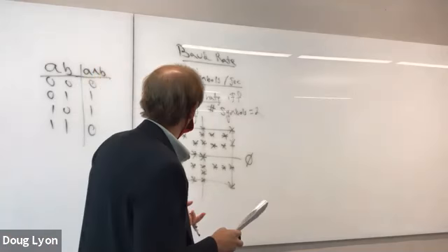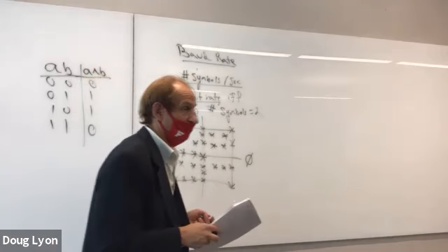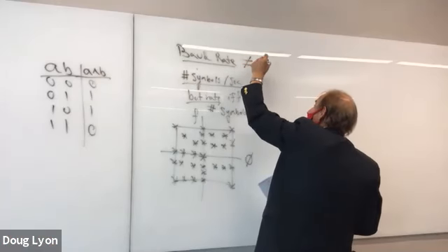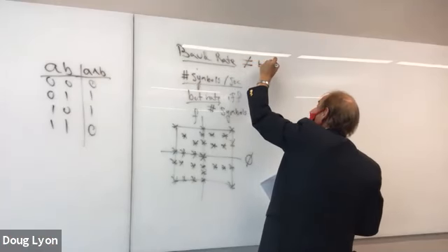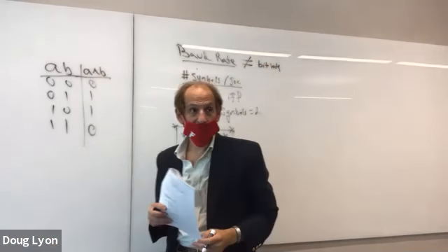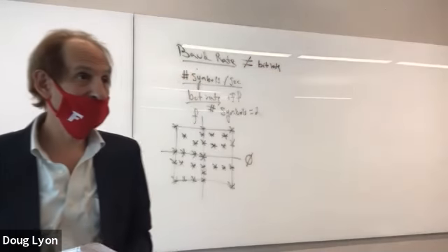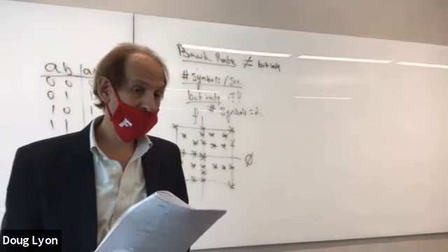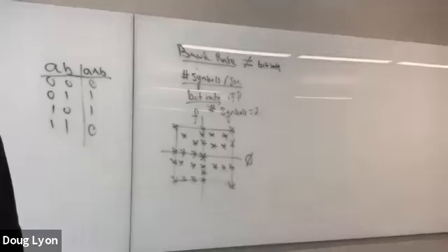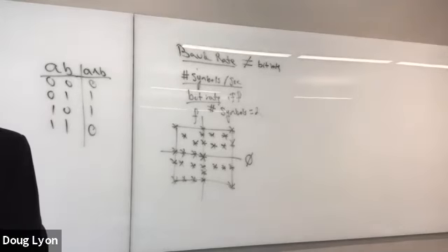So bit rate and baud rate are different. They don't have to be, but in general, it's not equal to the bit rate. It's equal to the number of symbols per second. And if you know how many bits you can get per symbol, then you can know how many bits equivalent you're going to be transmitting per second.